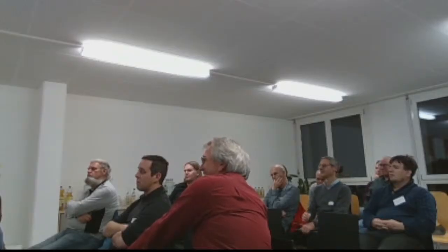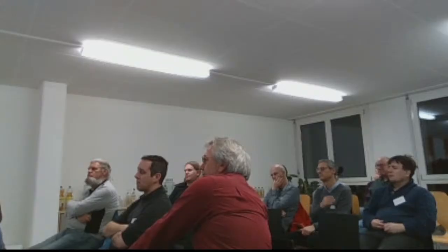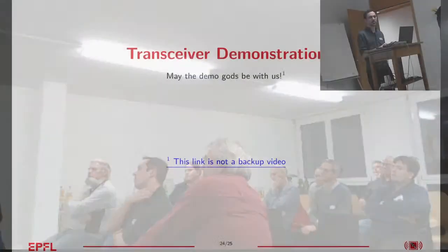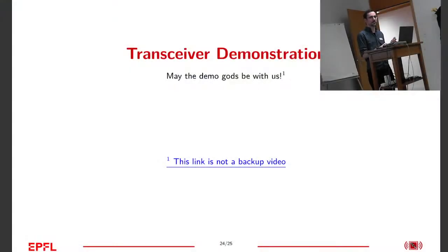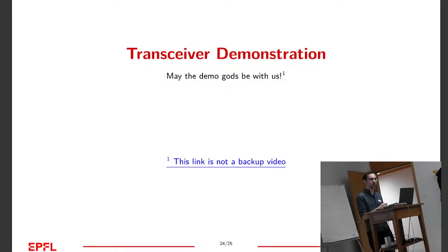If you install a standard LoRaWAN stack, then the stack makes you respect the 1% duty cycle, but it's open source most of the time, so you can always tweak it if you don't want to follow it.